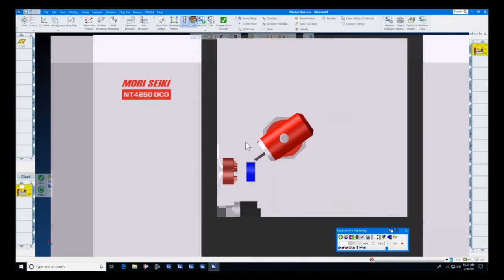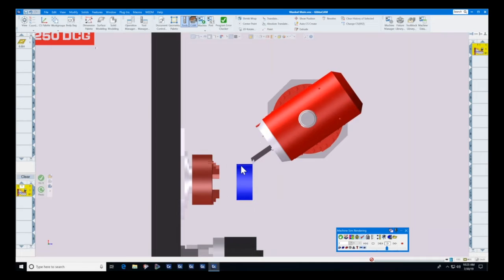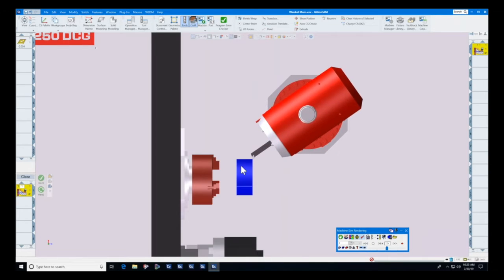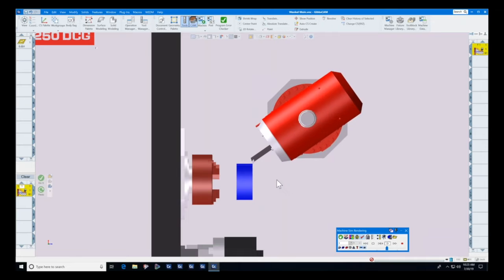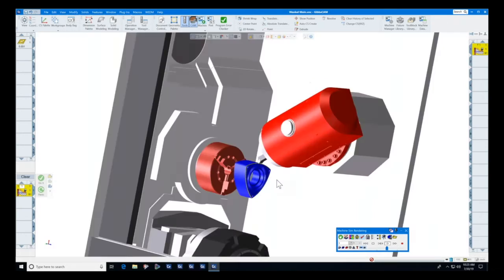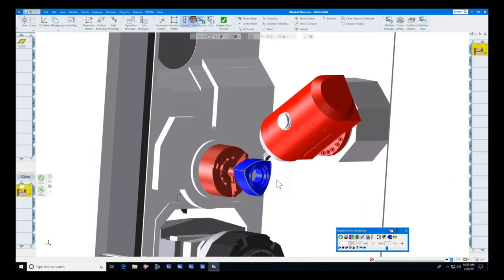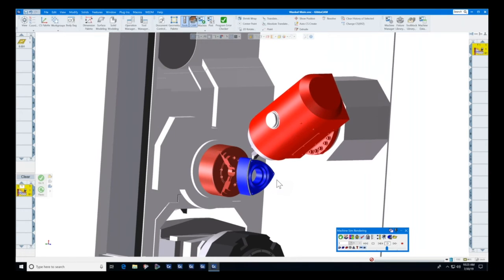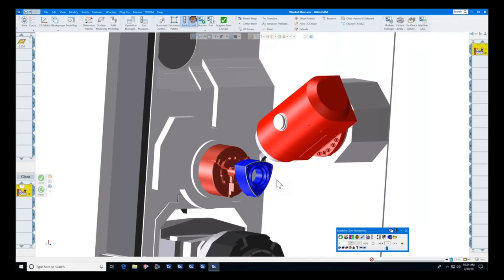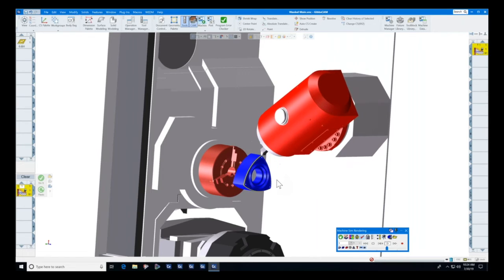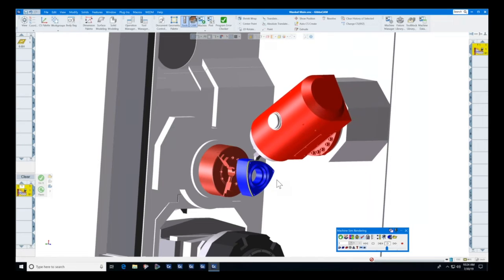of 35 degrees. And if your machine has TCPC and dynamic work offsets, then this is a non-issue for you. There's no more action needed other than to repost the code and put it into the machine, and you can now cut with this tool at a new angle. Now, this will become important to us later when we talk this morning about volume mill turning.